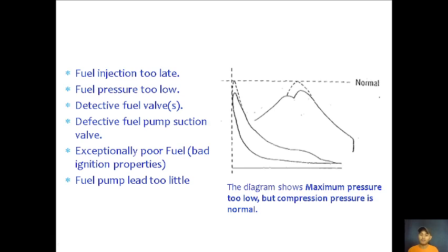Defective fuel valve. If your fuel valve is defective, it will have a late injection. Defective fuel pump suction valve. If the suction valve of the fuel pump has a problem, you cannot activate your injector or your fuel valve on time, so there will also be a delay in injection.